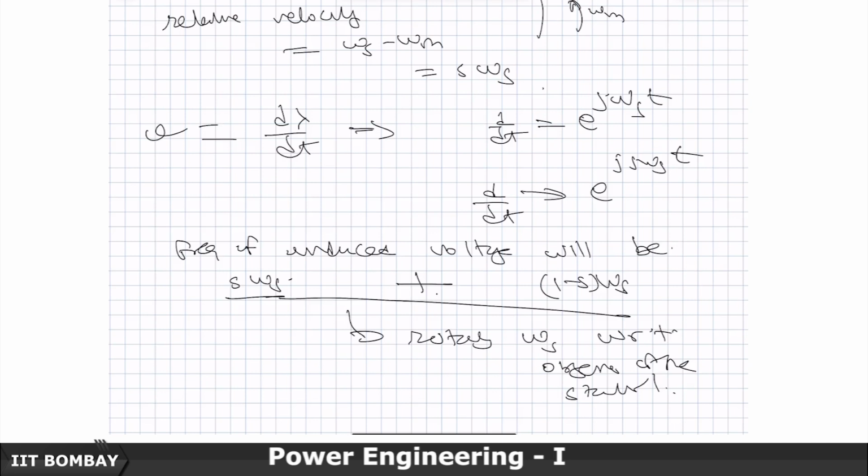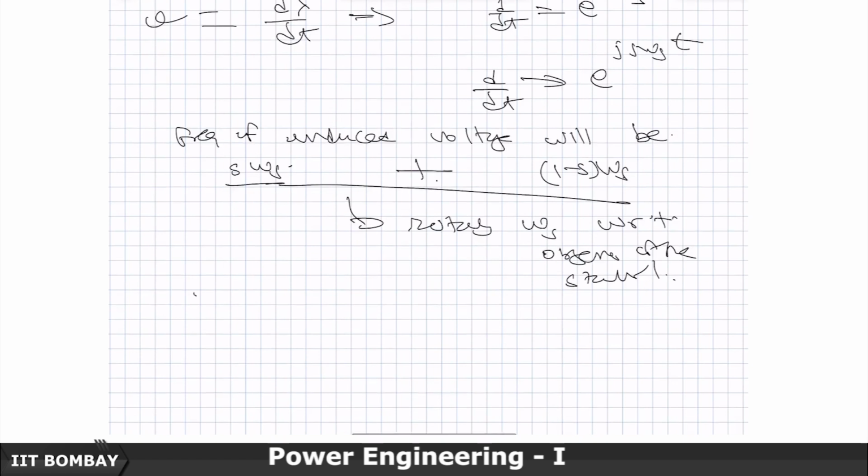The first information that I have given you is that in the rotor the voltage induced will be of frequency s omega s, and therefore the EMF induced now will not be E2 but sE2. Where did this come from? This came from the fact that RMS voltages induced in transformer windings are given by 4.44 f N2 phi m.